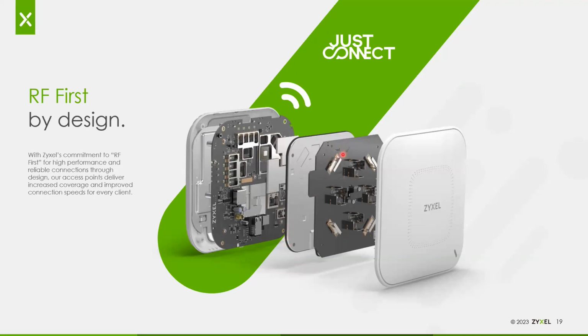The last thing we do, which is very different here, is we don't mount the antennas directly onto the PCBA like most of our competitors. Instead, our antennas are usually mounted on their own board that is separate from the main PCBA, and there's generally a shield between those two boards. That provides just that much better isolation for these antennas from any sort of EMI that might be coming off the main board. And this other board also acts as a reflector to help strengthen the signal coming into the access point. So that gives you a little bit better signal to noise ratio for that much better of a solid connection, especially for those weak clients.